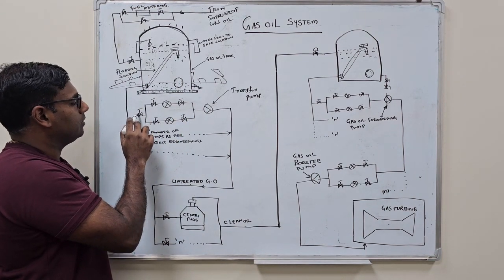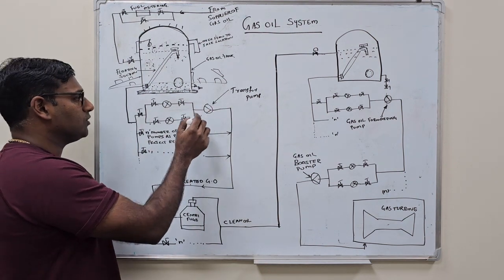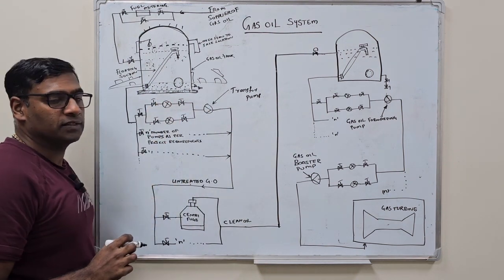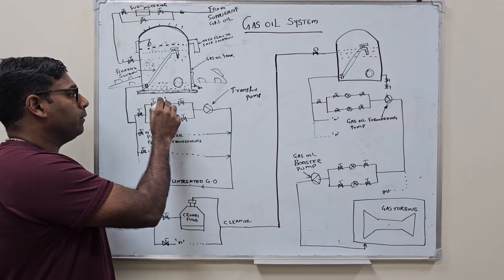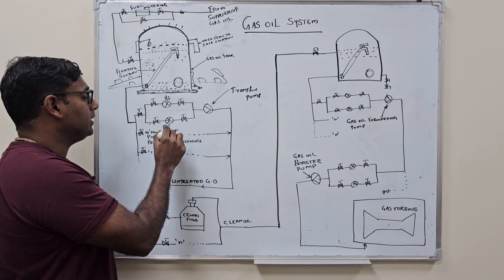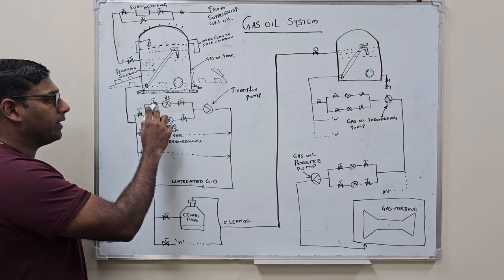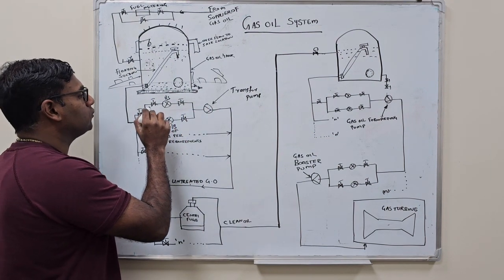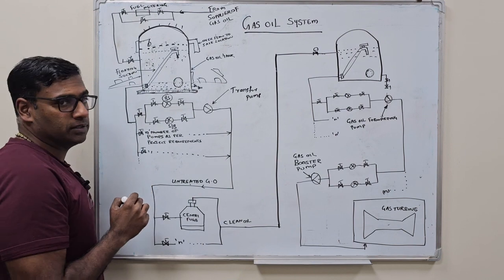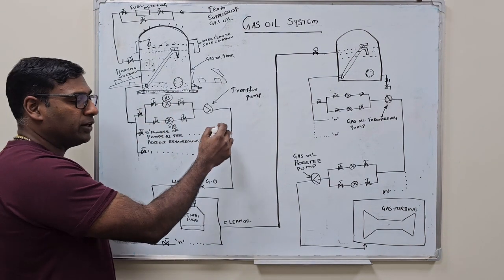The oil comes here. We have provided an isolation valve for the system. Most transfer pumps are equipped with a duplex filter mechanism. It means there will be two filters, and one filter will be in service and the other one will be on standby. So there are isolation valves provided across the filter ports. So if this pump is operating, one of the filters will be in service. Let's say this filter will be in service, so these valves will be in open condition. So the pump is running 24/7.